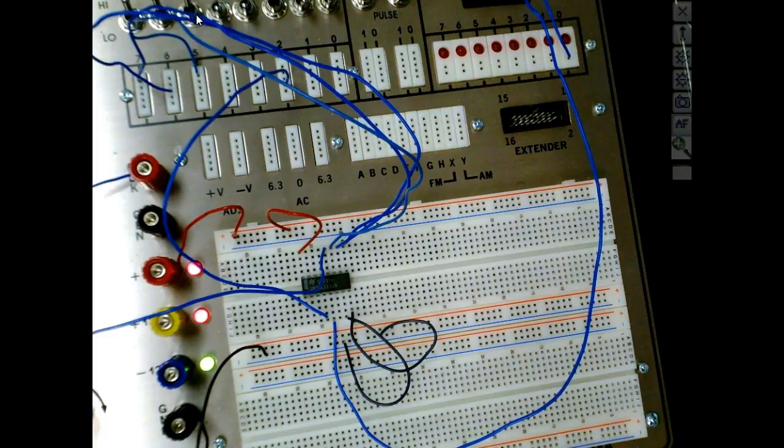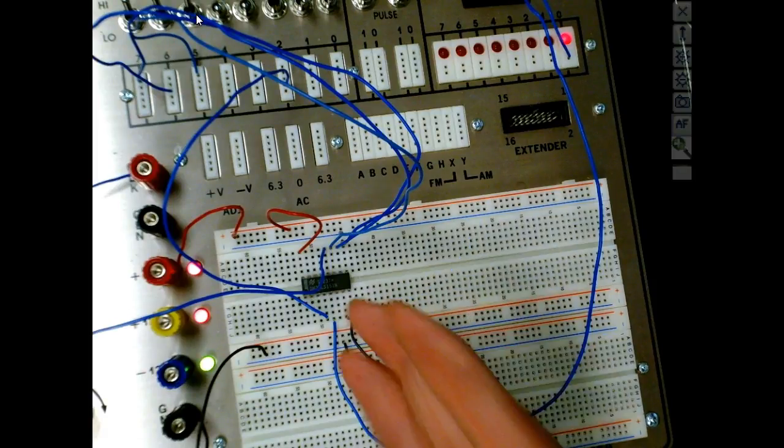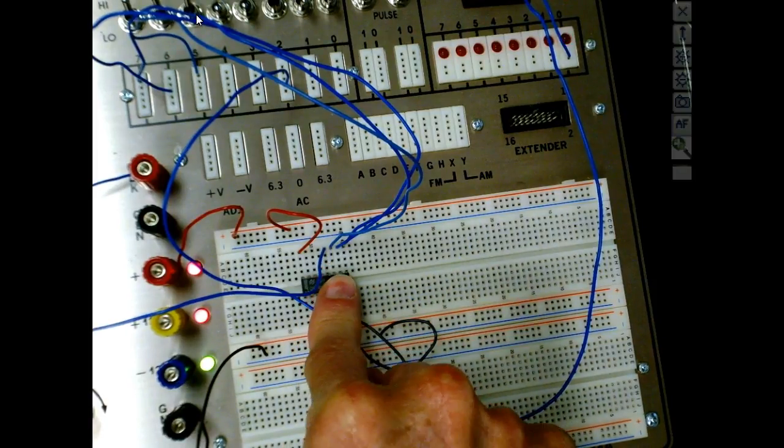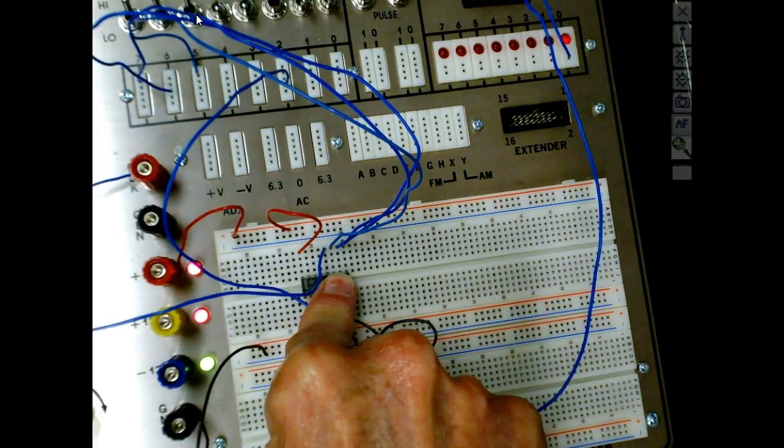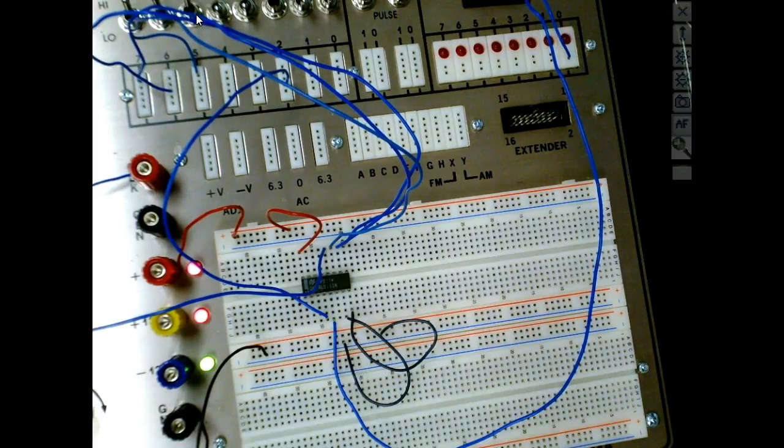Now, step 3 says do what? Open some of the inputs and see what happens. So what's an open input on a 74151? What's it taken as? It's taken as a high, right? Let's make sure we did that. We did step 1, we built the circuit. We built step 2, we built the circuit. Step 3, we opened some of the pins, right? It says open some of the data pins and open some of the address pins.